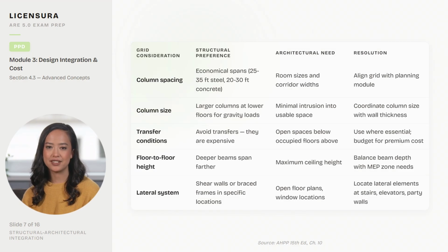This list details 6 elevator integration requirements that affect architectural design. Machine room-less elevators still require overhead space and pit depth, even without a separate machine room. Elevator lobbies may be required for fire service access, depending on the code. Shaft walls are typically 2-hour fire-rated construction.